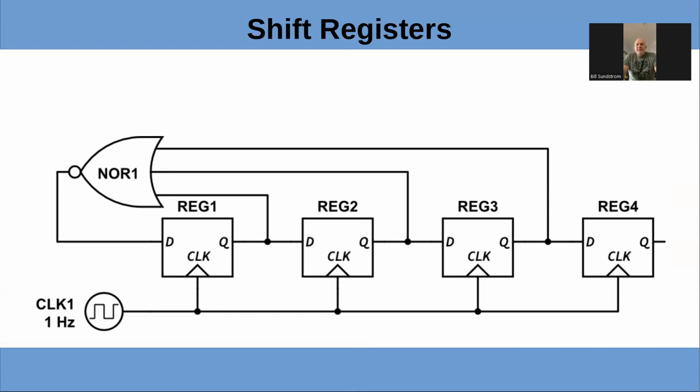So each one of those flip-flops is a power of 2, and you're multiplying it. So a 3-bit counter will give you 8. If it was a 4-bit counter, what would it count to? 16. Actually, it counts 0 through 15, and on the 16th one, it goes to 0. Got it.